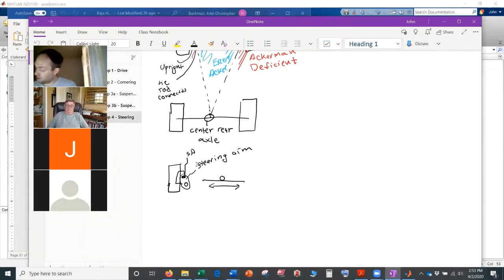And then you'll connect between here and this point, it'll be your tie rod. And that'll move, and so that's how we typically move our system left and right, basically, right? And sometimes, if it's just a part of the upright, it's basically your tie rod connecting point. A lot of times when we refer to it, it'll be like, where does the steering arm connect with the tie rod, right?